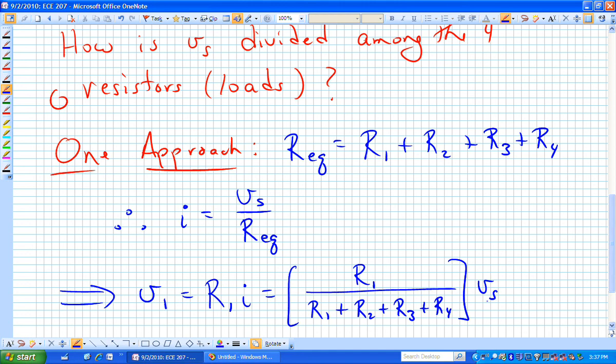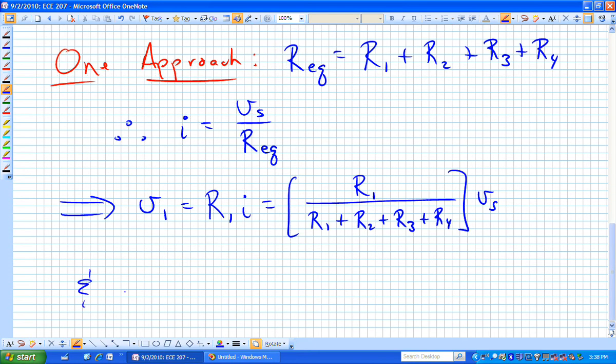How do you see that formula? Well, you see that you needed all of the resistors in the bottom, and that basically, when divided into the voltage, gives you your current. And then whichever voltage you're interested in, the voltage drop across R1, R2, R3, will depend on what's in the numerator. If you're interested in the voltage drop across R1, you just take R1 times I. And so R1 is in the numerator. Meaning, now you have the generic formula V sub I is equal to R sub I times I.